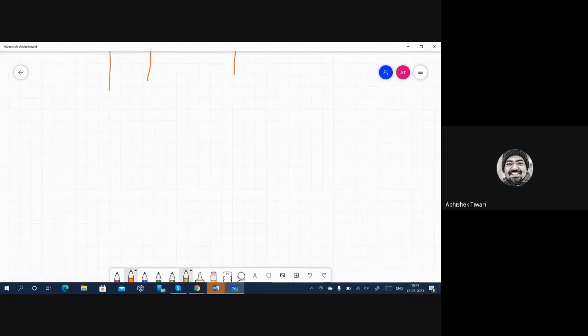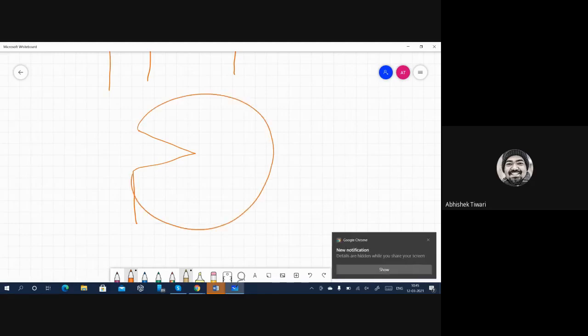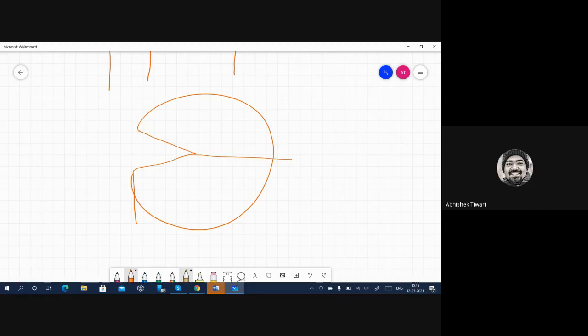Now what we will do in modeling, we will make a circle instead of making a cylindrical specimen. We will put a crack. So we will make a circle like this, and we will partition it. If you remember, how did we do partition? We will partition it at different angles. So we will partition it at theta equal to 5 degrees, 10 degrees, 15 degrees, and so on. So with an interval of 5 degrees, you can partition the whole circle in different ways.